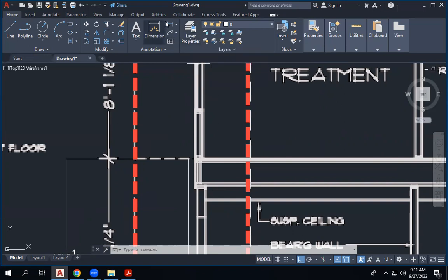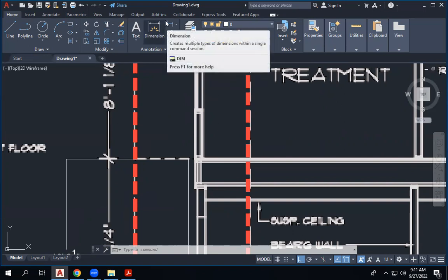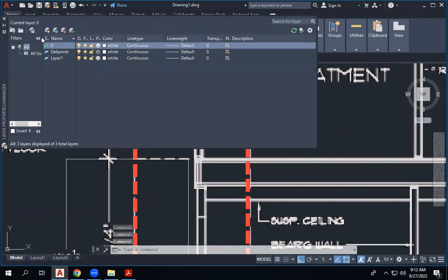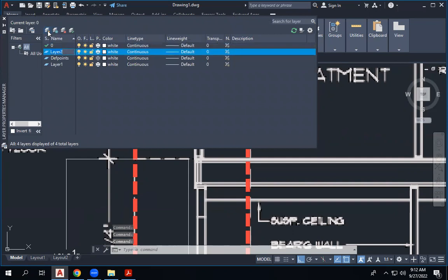After you draw this and when you make a PDF, if you think that a line thickness is thicker or thinner, you can change it. You just come into the layer, open the layer properties, and just change the thickness. That's it. The layers will be there. Then it's easy for you. So I'll also try to make four layers here. I'm using 0.35, 0.2, 0.1, and 0.